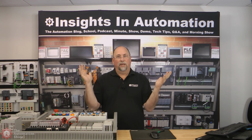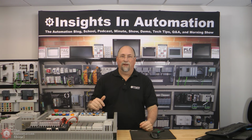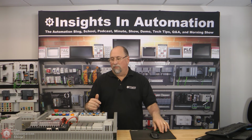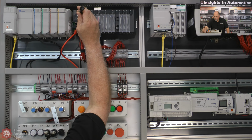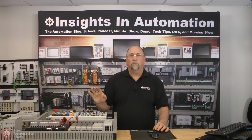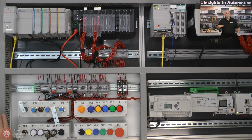So I thought, hey, it has BootP. Rockwell people are used to using BootP for decades now, right, to assign addresses to the PLC parts. So let's go ahead and set it for BootP. So I'm going to go ahead and tweak this in here. Okay. And so now it's set for BootP, and I'm going to go ahead and power it on. I'll be right back. Okay, we can see it booting up. So let's go over to the